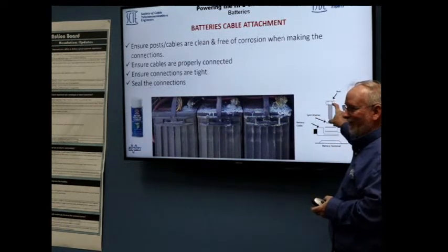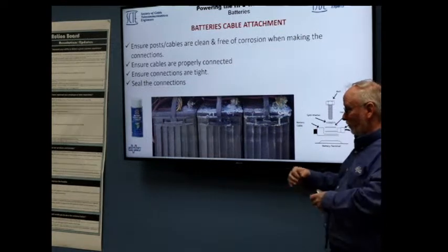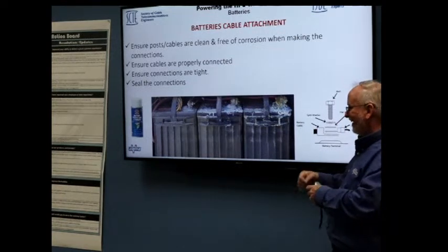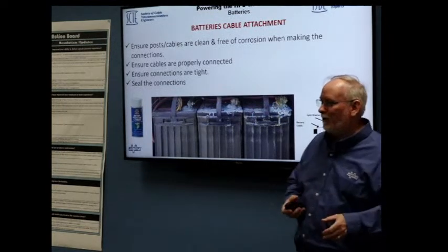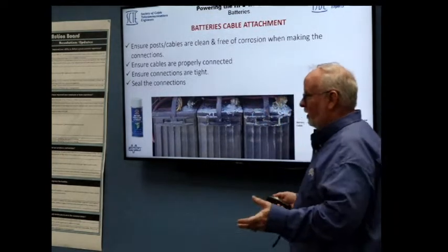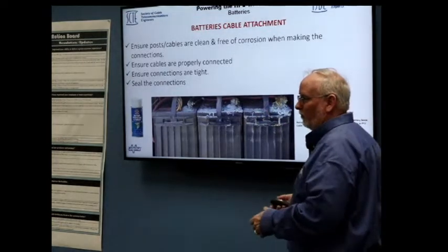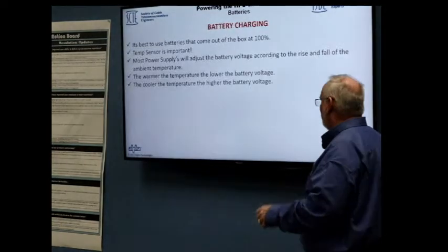Use the right bolt. If you use the wrong bolt, it will get really hard to tighten at the end, but you can keep tightening it, and what you'll do is you'll shove that thing right into the battery itself, and things will not end well. Most of the time it just breaks it. Sometimes I've seen it actually go far enough down to cause other damage.